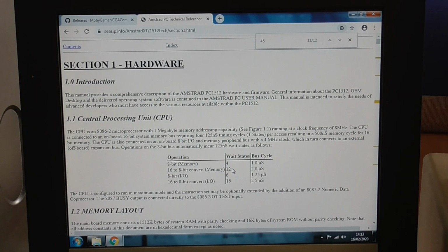So a no-op is 3 cycles, but you also have a bus access of 4 cycles per no-op. So this is significantly less than the 46 that was promised, but at least it's something. And I realized that it must correspond to the horizontal retrace.